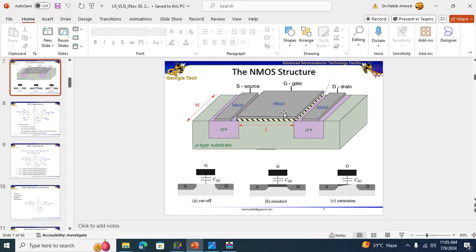Under normal operation under zero applied bias, this structure is going to be in cutoff, which means that the drain and the source are disconnected. We don't have a channel that connects the drain with the source. However, when we apply a positive potential to the gate above the threshold voltage, it's going to attract electrons from the bulk of the material, forming the channel between the drain and the source, turning on the transistor. Now, this is the structure of the conventional field effect transistor based on silicon.